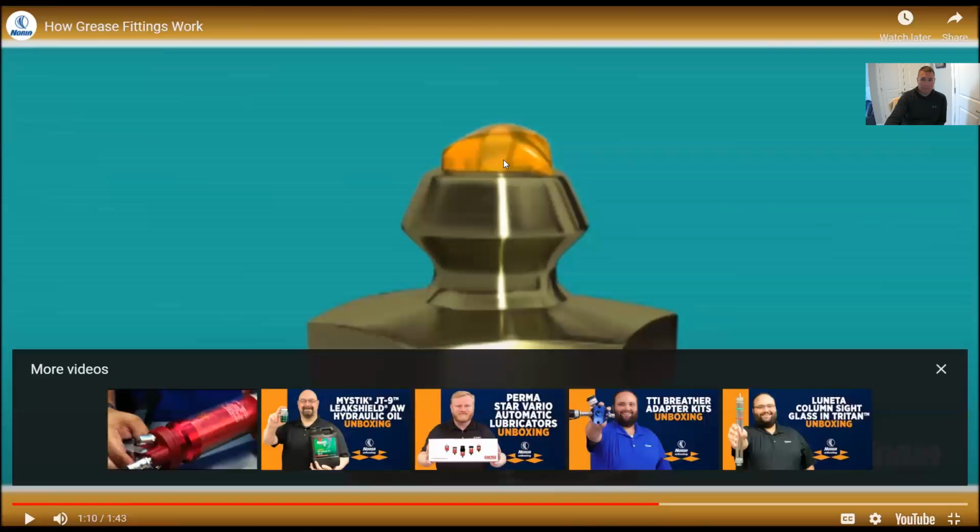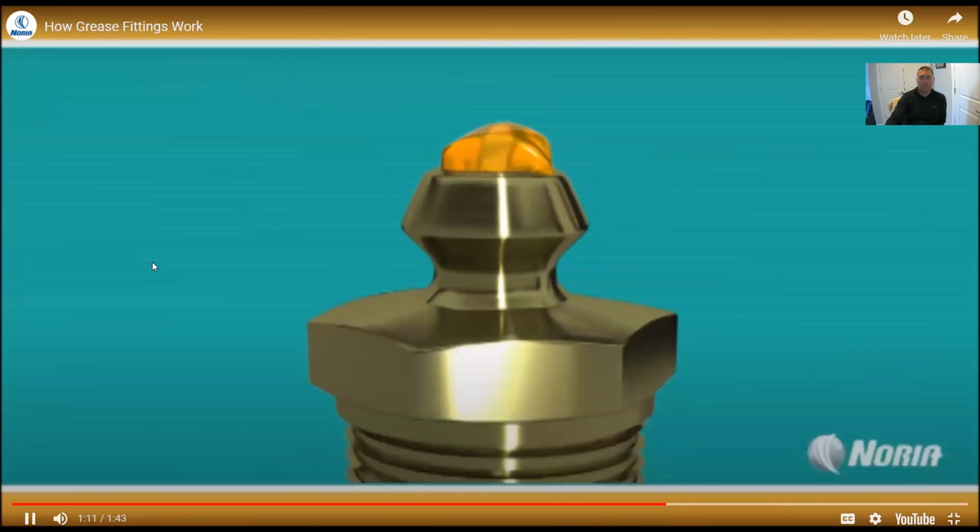If that stuff's getting inside this fitting, inside that joint, that's not good for your machine, okay? So keeping that clean will help you visibly see if that thing's working properly. Obviously, when greasing it, you'll be able to tell if it's working properly as well.